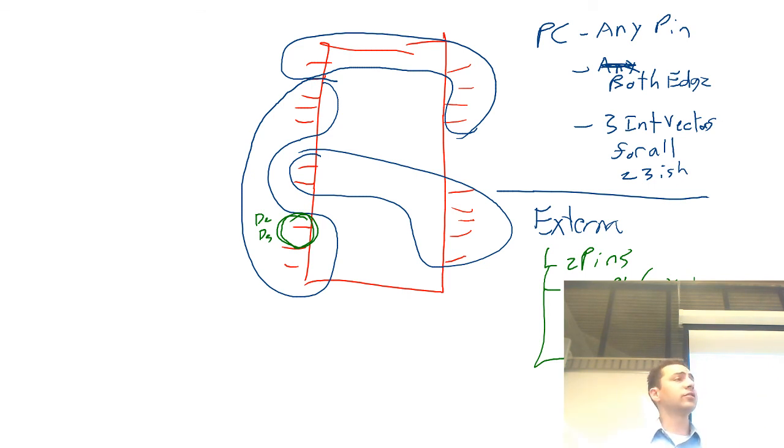So they're a little asynchronous. They don't necessarily rely on the system clock, whereas pin change interrupts do. The system clock has to be running for that to work. But the main difference is each pin gets its own interrupt vector. Okay. Those are the big differences. So pin changes can happen on anything, but you must deal with a trigger on rising and on falling. Whereas external interrupts only happen on two particular pins. There's an interrupt for each pin, and you can choose how they fire.